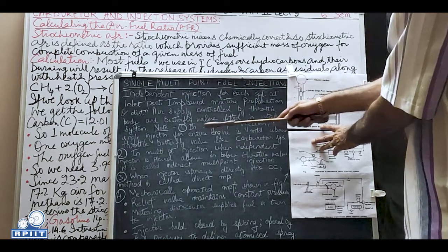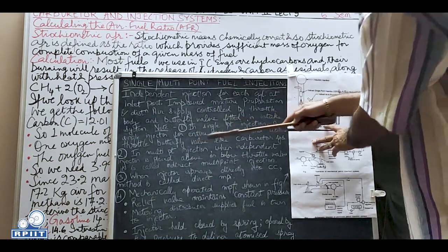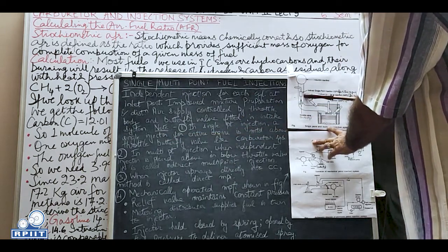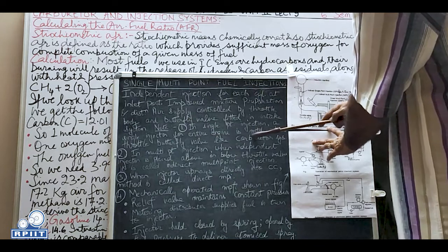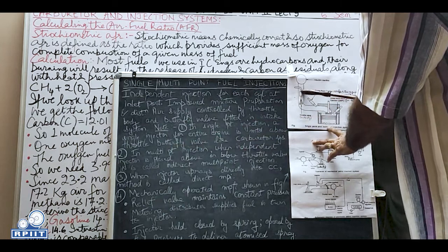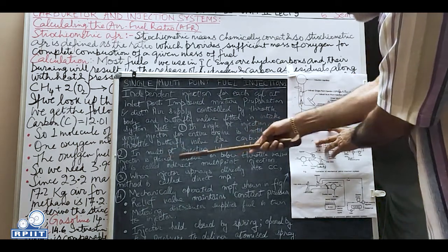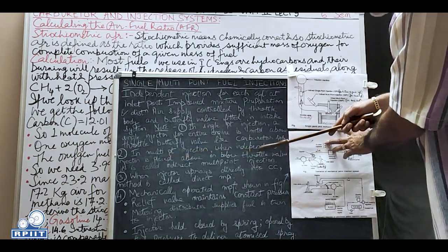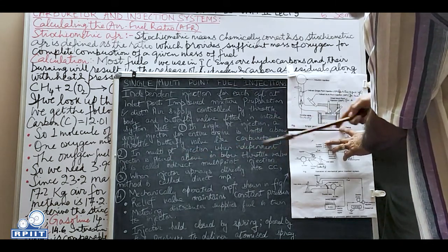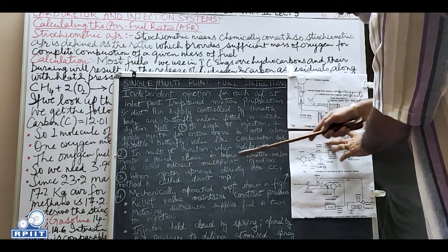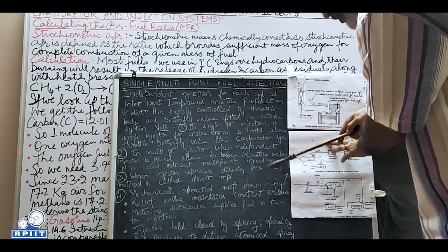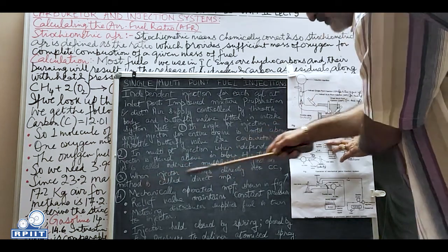Note, in single point injection, a single injector for the entire cylinder set is mounted, as I mentioned. It is mounted above the throttle butterfly valve, like a carburetor system. In multi-point injection, when an independent injector is placed above or below the throttle valve, it is called indirect multi-point injection. Third, when injectors are placed directly into the combustion chamber, it is called direct MPFI.